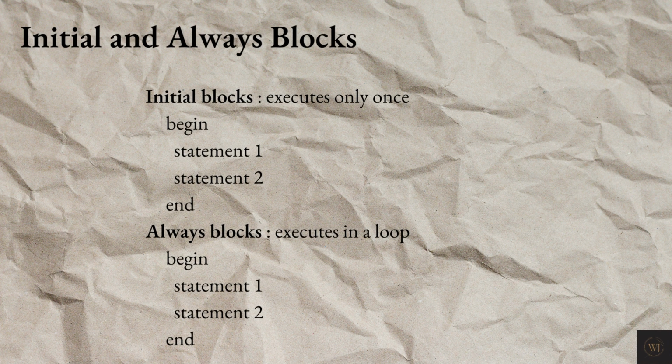In Verilog coding, there are two blocks used, which are the always block and the initial block. The initial and always constructs have the same form, but statements inside initial are executed only once, at the start of simulation. When multiple statements are included in an initial or always block, begin and end are used.